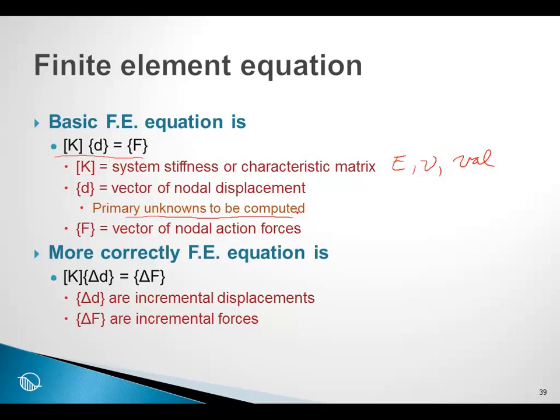And those of you who have been part of other sessions will already recognize the form of this equation is essentially the same in all finite element analyses. However, in this case, in SIGMA/W, it is more correct that the finite element equation is K times some incremental deformation is equal to an incremental force. And this is what we mean when we say that SIGMA/W is based on an incremental formulation.